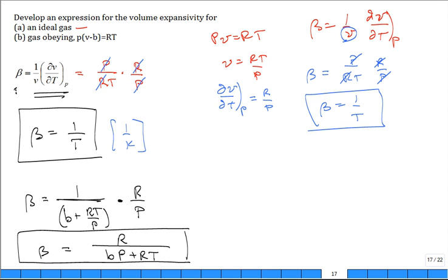When I teach heat transfer, I'll say 5 times, the temperature must be absolute temperature. And then I give them a problem. I say calculate beta when the air temperature is 20 degrees C. And you know how many students on the final exam in heat transfer put 1 over 20 degrees C? So I tell you in heat transfer, beware of that trap. I tell you in thermodynamics, don't make this mistake, right? So there you go. This has to be absolute temperature.